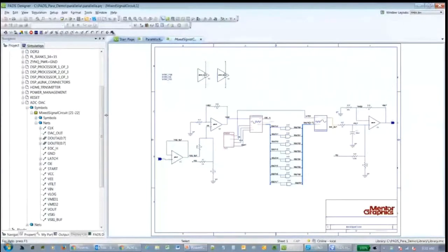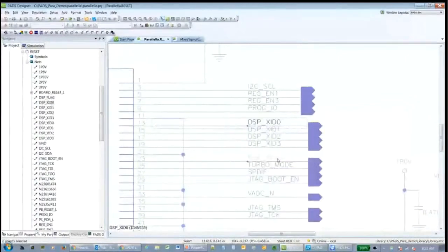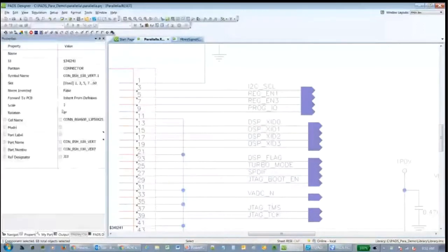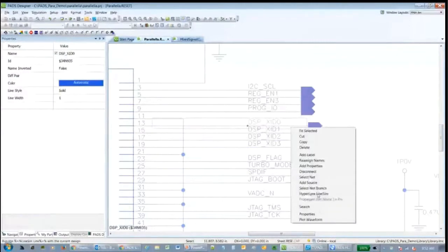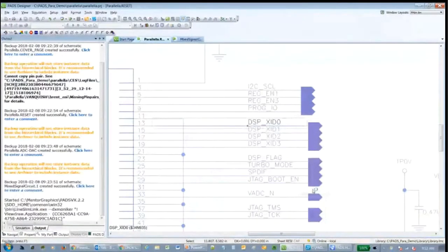and we'll just select a net like this DSP output here. Now let's say I'm worried about this line in my design for some reason for signal integrity. Right here in the schematic, after I've captured this, if I've assigned IBIS models to my part here, which I haven't in this case, but if I did, when I right-click over this and say I want to take this into our pre-schematic environment, what I can do here is see the topology of this net. This is a multi-drop. Actually, it's got 2 nets on it, a connector and a couple of resistors.